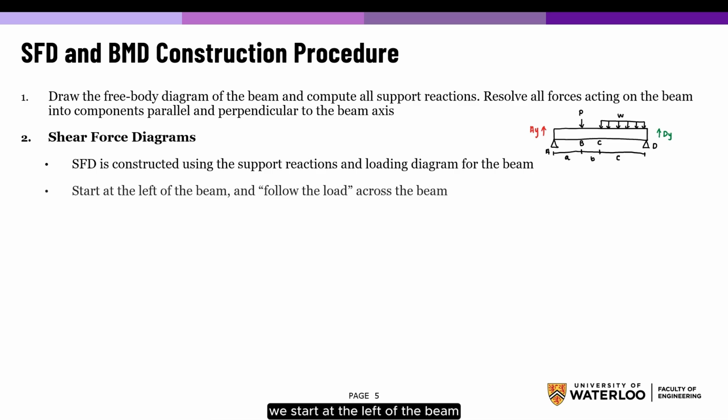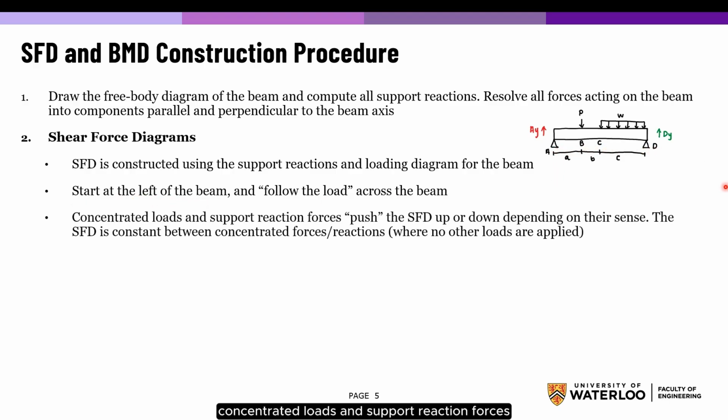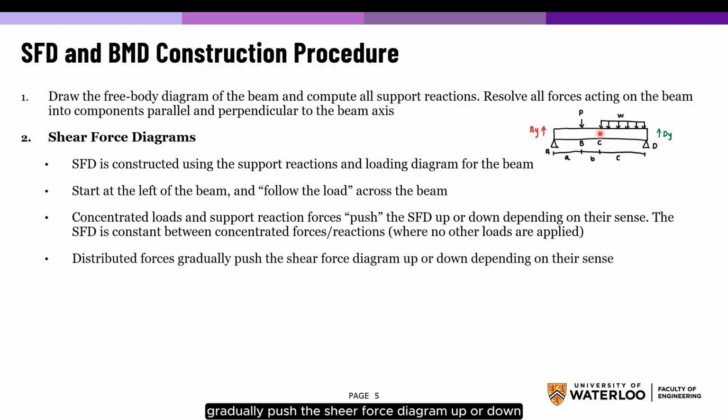Shear force diagrams are constructed using the support reactions and loading diagram for the beam. We start at the left of the beam and follow the load across the beam. Concentrated loads and support reaction forces push the shear force diagram up or down depending on their sense. The shear force diagram is constant between concentrated forces and reactions where no other loads are applied. Distributed forces gradually push the shear force diagram up or down depending on their sense.